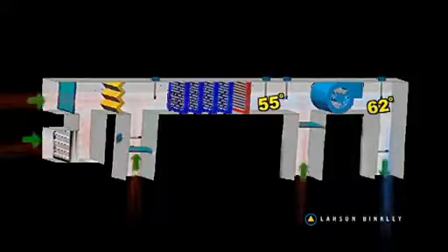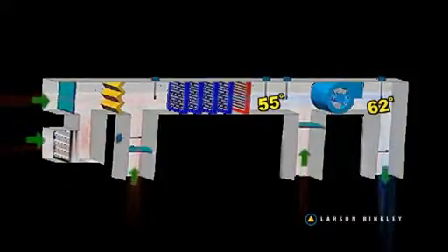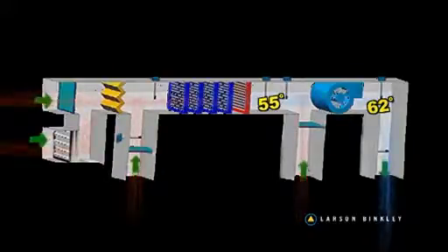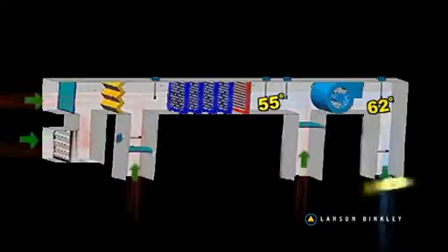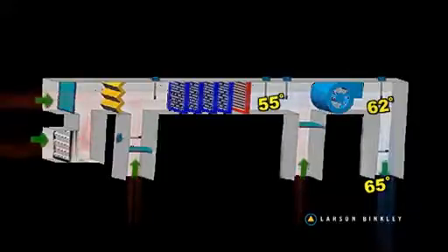You would be very surprised to know that only 10 to 15% of the total CFM supplied is bypassed return air for bringing the supply air temperature up to 60 or 65 degrees at peak load. The load in the space is the same for an underfloor air system as it is for an overhead mixing system. The difference is in how we handle the load.